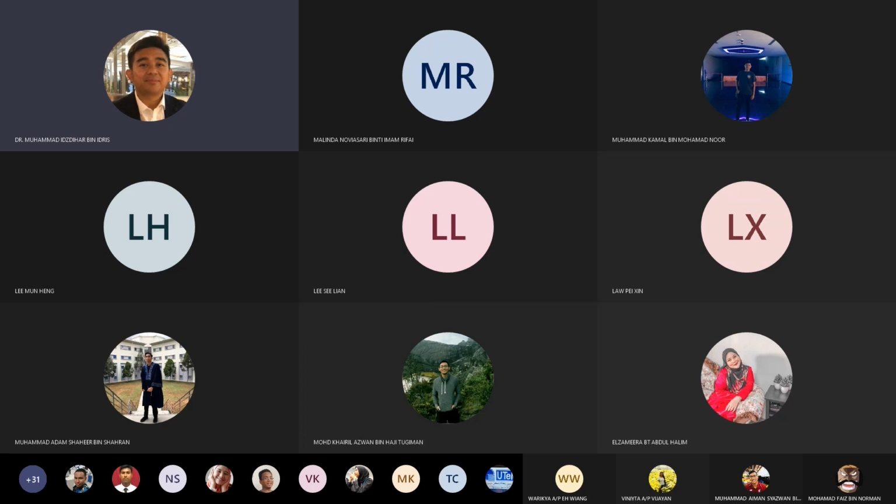And pull down must be connected to ground. So your pull up must be connected to VDD. So you have one output which is Y in this case, and you have 2 inputs A and B. So this one is A, this one is B. So B can also go here, and A can also go here. Okay, let's say when you have 0, 0, your input are 0 for A and 0 for B.